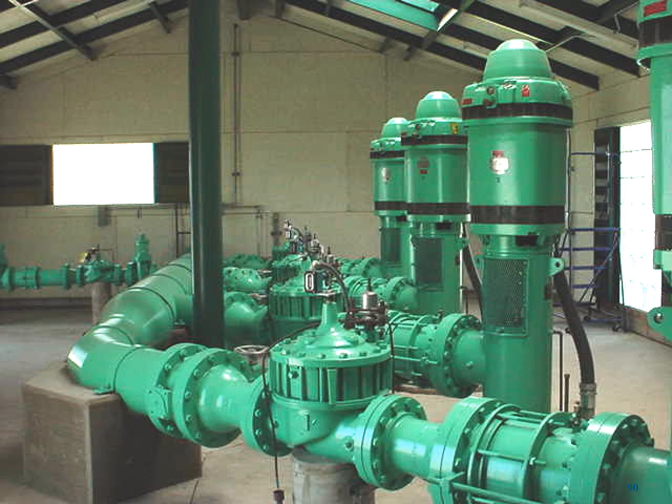So in this image, I've got a nice indoor pump station here, lots of working room to get in and around these pumps. On the top of the pump, you've got your motors here. There's four of them, and then you've got this little sight glass up near the top, and that's an oil level sight glass, so that we can see, do you have the proper amount of oil in there? You're not too high, not too low.